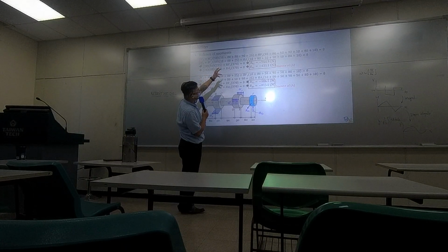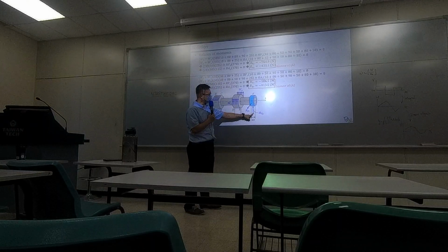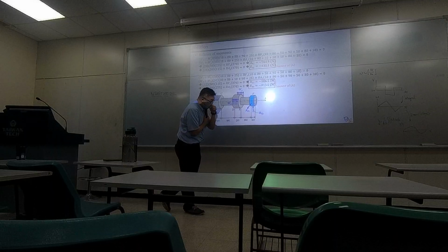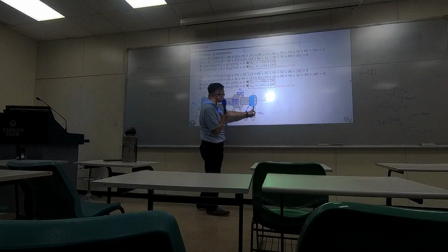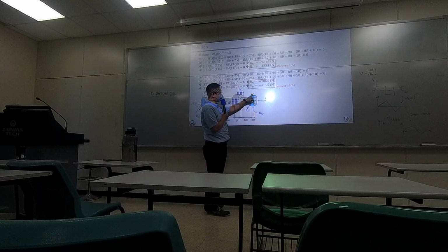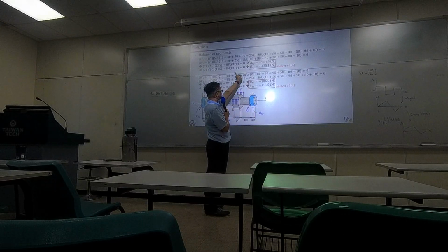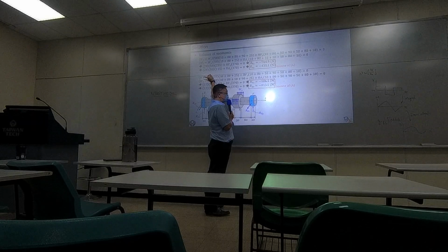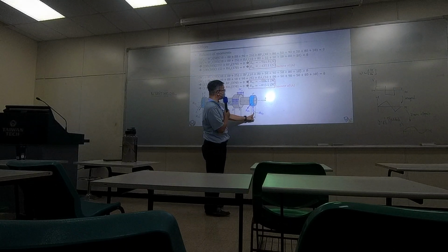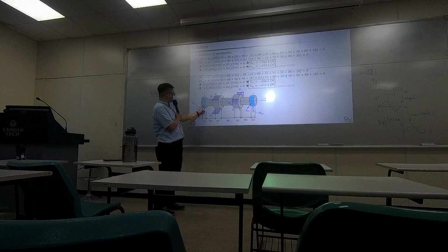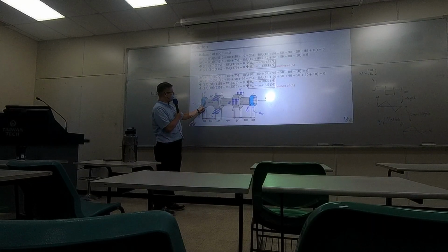That would be balanced out by the reaction force right here. Sorry. Since at the beginning I drew this along the positive direction, it's also generating a counterclockwise moment. So RFY times half of it, so the support is right at the middle here.